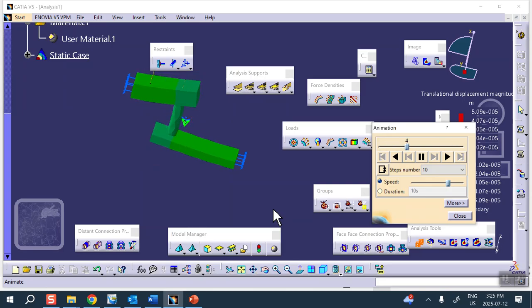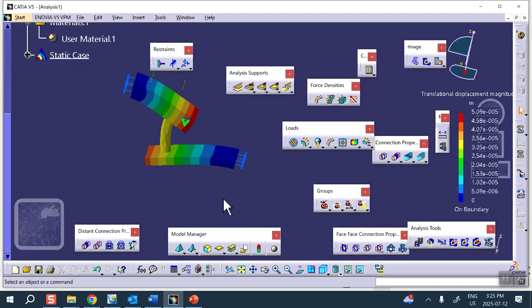But then, in order to mesh it, this one way is to add all these things that are created into the part body, and then go ahead and do it. Now, in the meantime, notice that material property was lost, so I had to go and create a user-defined material, and then apply 3D section into that using that user-defined material. All right. Good luck if you ever need to do this.